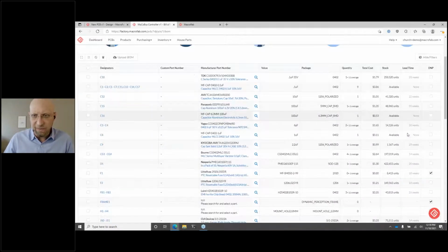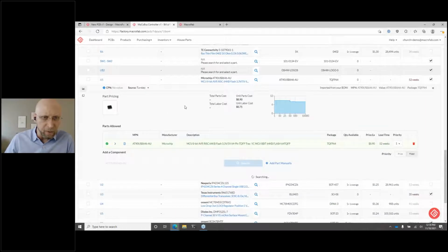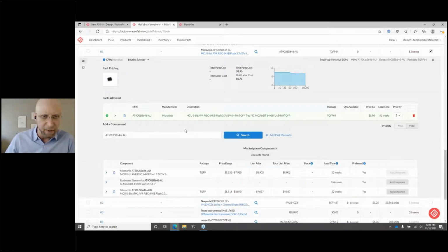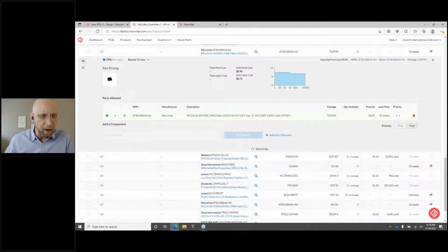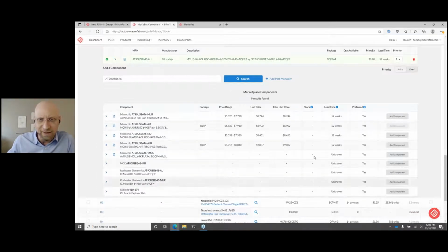For example, if I have a requirement for a part in my design that has a 52-week lead time and there's no stock available, let's take a look here. We are looking for this particular microchip part. We'll see that there's no stock. It is a 1 year lead time. Let's look at other form factors. Take a look and see if there's anything else in any other footprints for this particular part. Here we can see that this thing is out of stock everywhere. It's not expected to come back into stock anytime soon. As an engineer, now I know that if I want to build this product anytime in the near future, I need to go select a different part, and I may need to change my design around this.